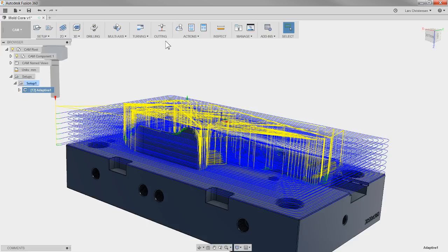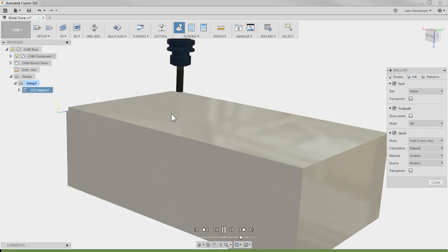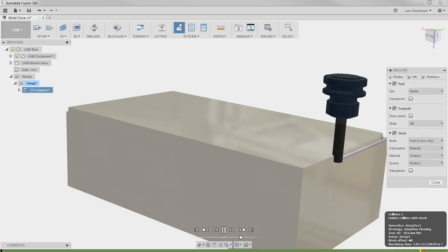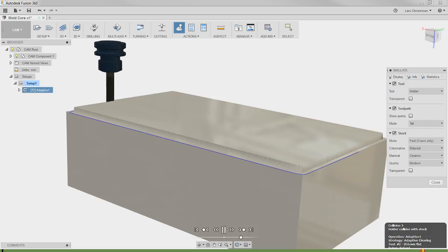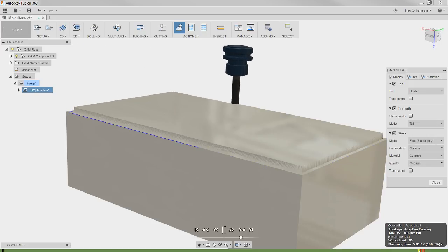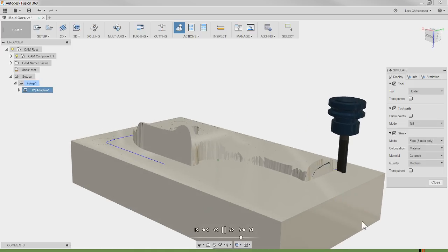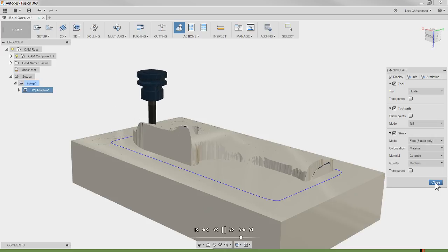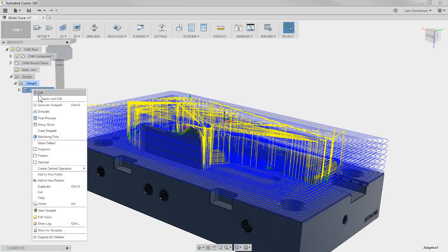Give me 1 second, there we go. If we go in and hit simulate here, and we start playing through, it looks like a lot of distance, right? A lot of chatter, but you will actually see down at the end of the cut, when it's almost roughed it all down, it will also hit. It will actually touch right over there. See how it turned red? So this tool here is not even good for that.